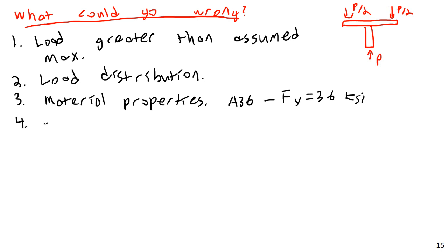What about manufacturing defects? What if the person I hire to weld this up doesn't do it right? If I was designing this, I would also prescribe welds. I would say I want a fillet weld or a full pen weld of this thickness, in these locations, of this length, that kind of thing. Well, what if the welder isn't very skilled, or maybe it's not their day, or maybe they make a mistake, and under the surface there are some defects that we can't see.